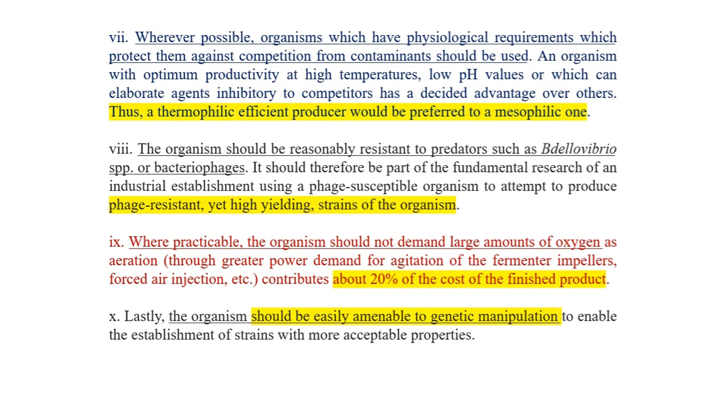And if your organism needs a larger amount of dissolved oxygen, maybe more than 80%, it is very difficult to maintain 80%, and you have to pump a lot. All that pumped air goes into a compressor, and the compressor passes the air into the sparger, and after that the bubbles are dispersed into the fermenter vessel by agitation using proper impellers. So many complications are there. So better we use a microorganism that utilizes the normal oxygen concentration, that is the dissolved oxygen.